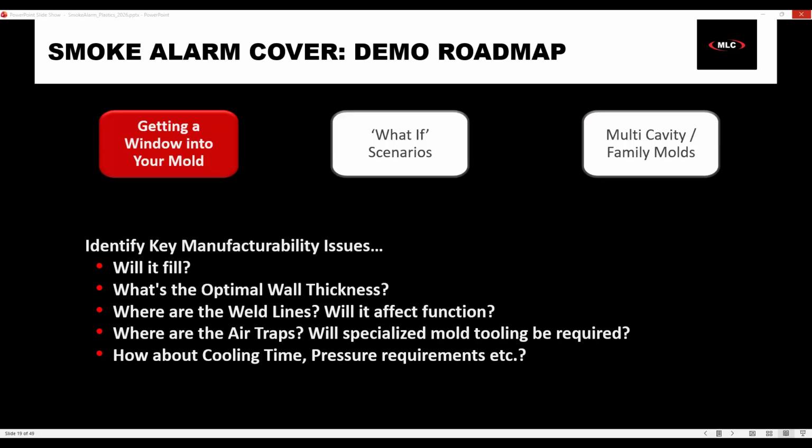A couple of things that we can do: if you go at the top under boundary conditions, this boundary condition up here and this boundary condition down here are interconnected, linked together. There is actually a tool called an injection location advisor. What this does is allow us to tell the system to automatically detect where this location should be.